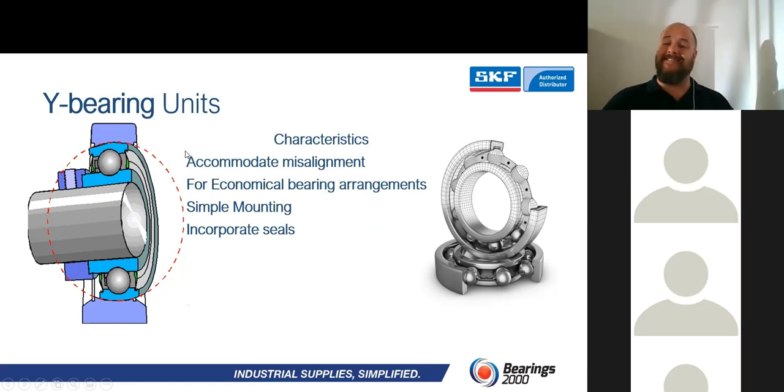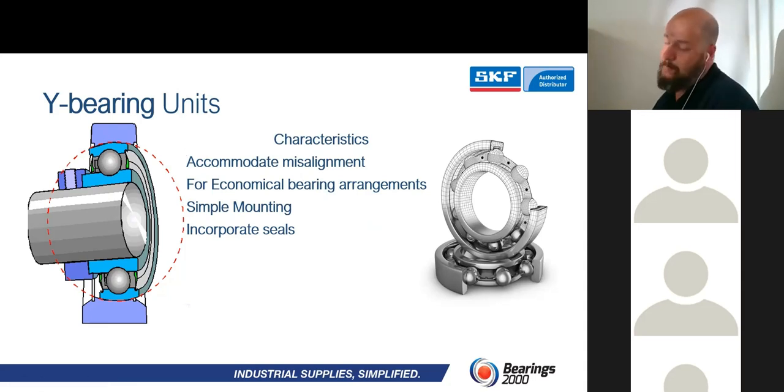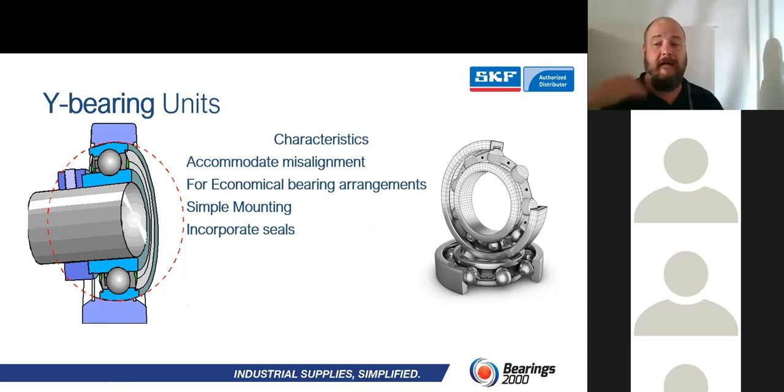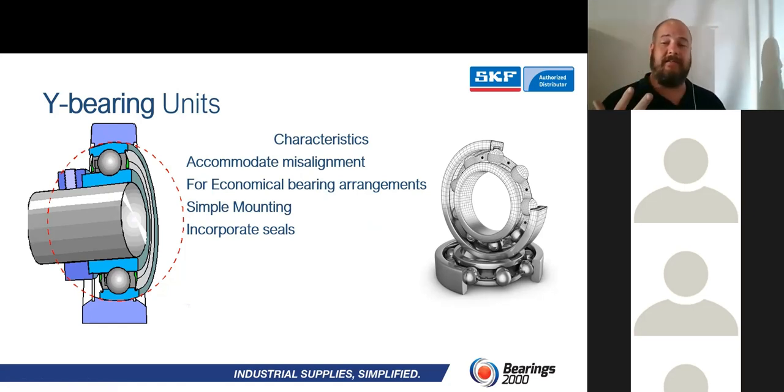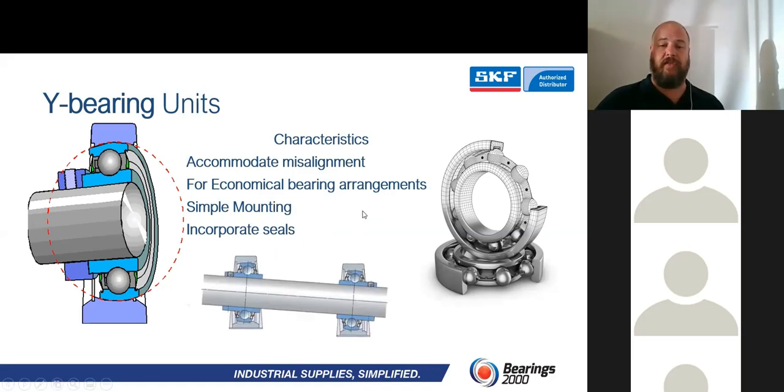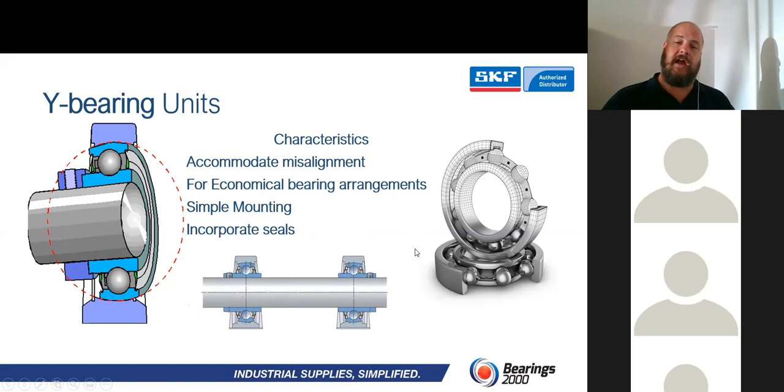If it is a maintenance-free unit, yes, maintenance free, guys, with a 5-lip integrated seal, ask us about that. If you want to know about these inserts, ask your Bearings 2000 representative anytime. Right. If it is a maintenance-free unit, you can get up to 5 degrees of misalignment out of these units, which is just mind-blowing.